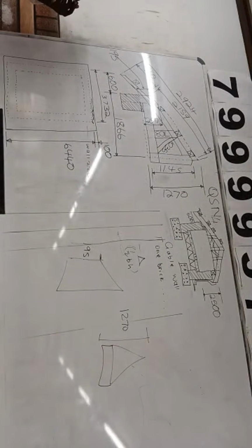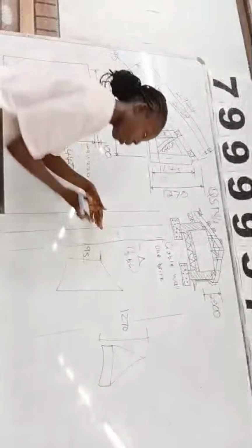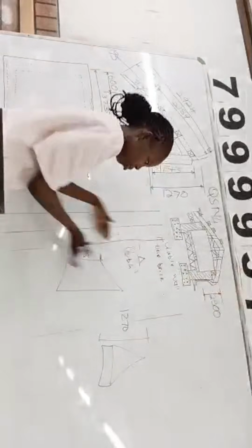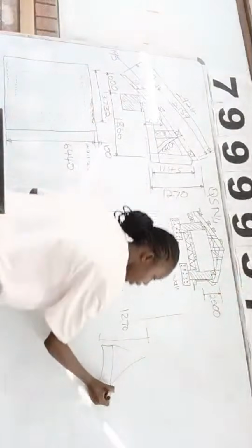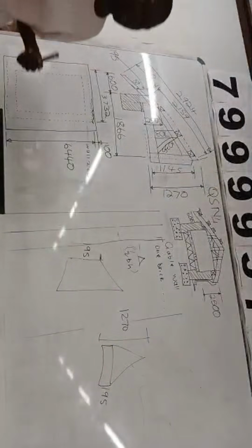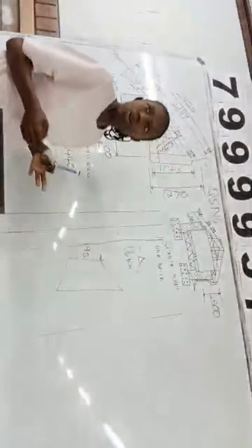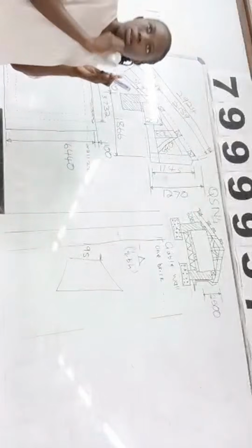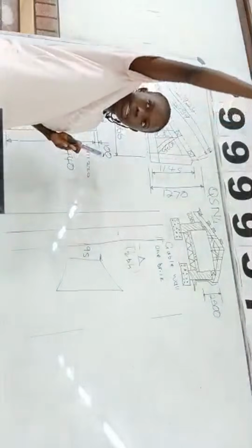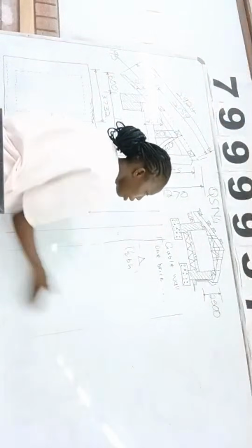The external one, you take the one that ends at this first corner, not the one where it's sloping, okay? So it's 195. And the 257, you will see where we are going to use it. So you just know it like that. My rectangle starts under the wall plate until that first corner. I don't take the long sloping line, okay?